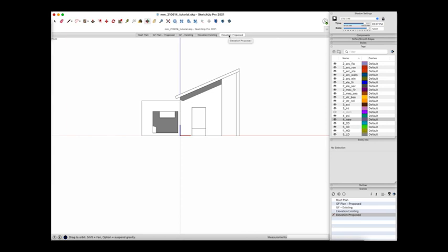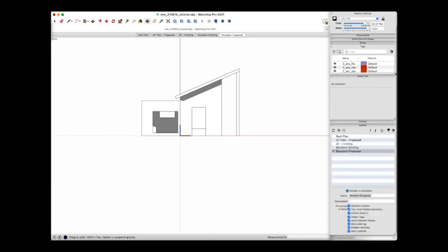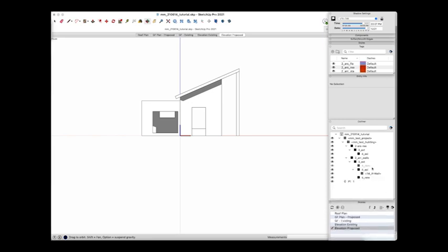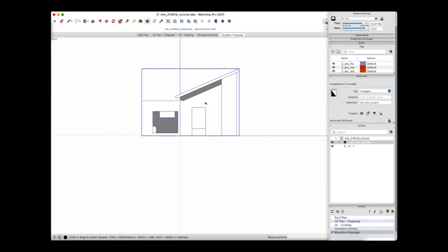The thing I wanted to show you really is how to model in a tidy way. So if you turn on your outliner, it's like your hierarchical tree structure for your model. It's really handy to label everything. And this also allows us to connect to IFC standards. So the entire project, which is here, is a component which is called mm_test project, and is defined as an IFC component as IFC project here.